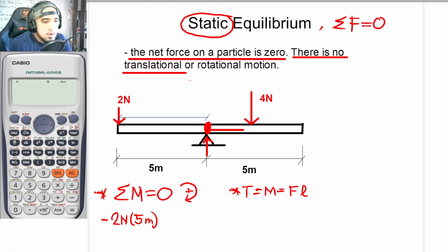Thus, this is now to be 2.5 meters. And if this force is to be applied, and if this is now to be the point and this is to be our imaginary stick, and we would be applying a force of 4 newtons, its tendency is to rotate in this manner. And this is now to be a clockwise direction. Thus, it would now be positive, since once again, my sign convention is clockwise positive.